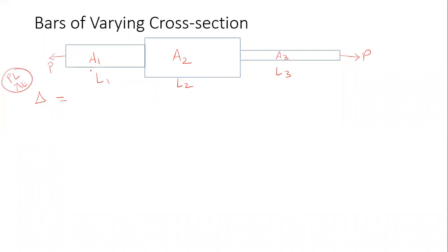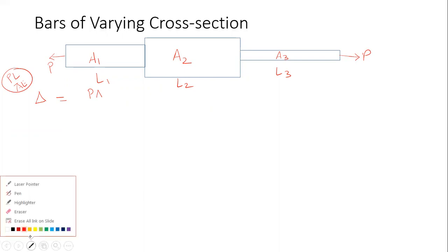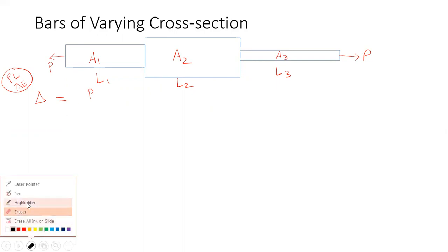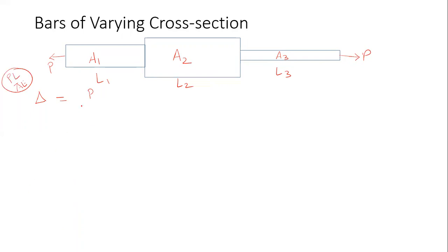So for this section, the total deformation will be P into L1, so this will be equal to P L1 upon A1 E